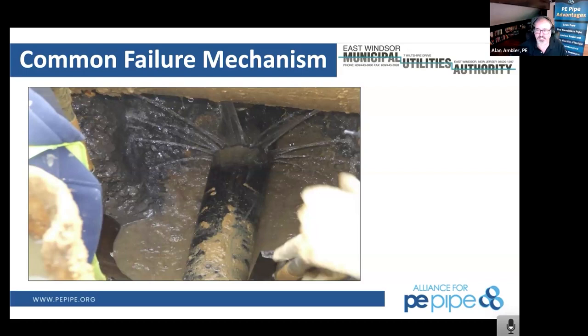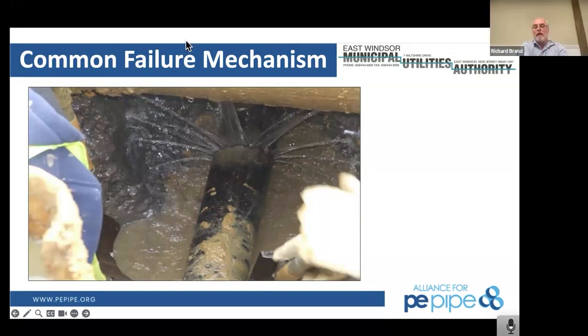And it's not just Richard that's experiencing this, especially in corrosive soil environments. Jared also said that they have 3,200 miles of water main, and they're getting longer life out of their non-wrapped ductile than their wrapped ductile. So that's interesting. It's not like they're making it up. So Richard, you're not alone. Yeah, the wrap is acting as a shield and trapping the water inside where the pipe is and the corrosion.